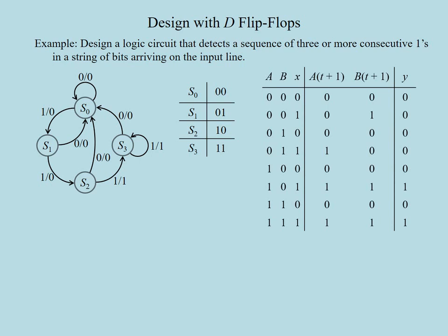With these values of the states, we can list the state transition table. Now, to draw the circuit diagram, we hardly need to write an excitation table because the input of a D flip-flop is required to be equal to its next state. We can directly simplify the next states of the flip-flops. In other words, we need to obtain simplified expressions for the state equations.